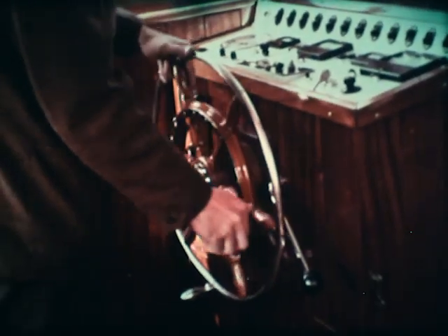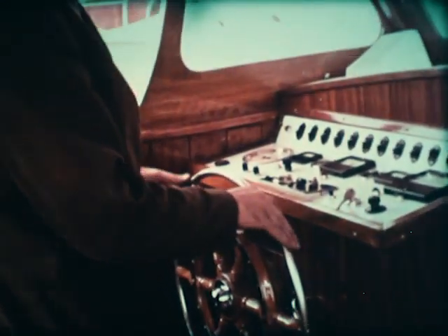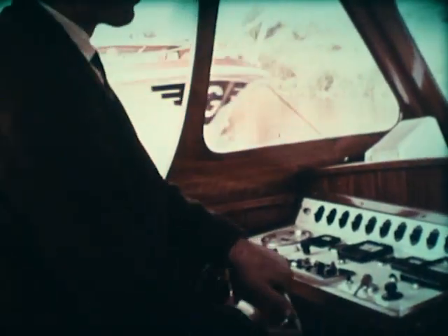On the other hand, by lowering the set speed, a dump valve is opened and a compressor pumps helium back to the pressure bottle. Moreover, a short-circuit valve is opened which makes a connection between the buffer space and the cylinder, thus momentarily cutting the power and giving excellent maneuverability to the boat.